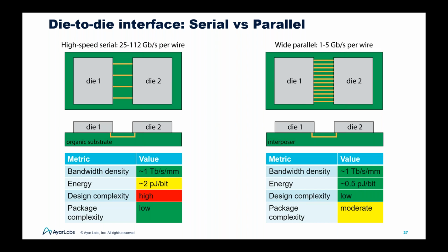Actually, no, because from the CPU, you're communicating with both sides as AIB, and that actually happens at 1 gig. You don't need to make it a serial link. It's a parallel link. No, I know that. But when you're on your silicon, you have to turn the parallel bus into transceivers to convert into the optical. Yeah, for example, in our case, apologies, guys, we are converting 25 gig, not 112. That's okay, so you're going a lot slower. All right, so apologies. Okay, fair enough.